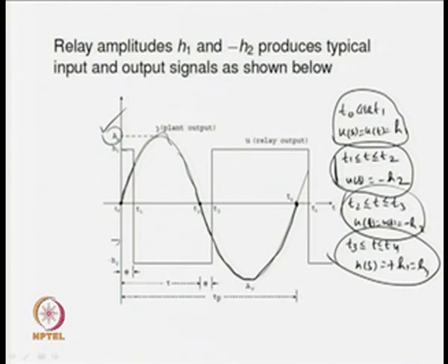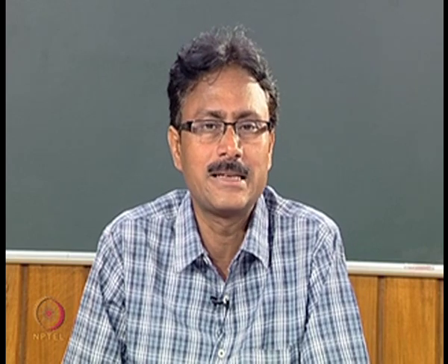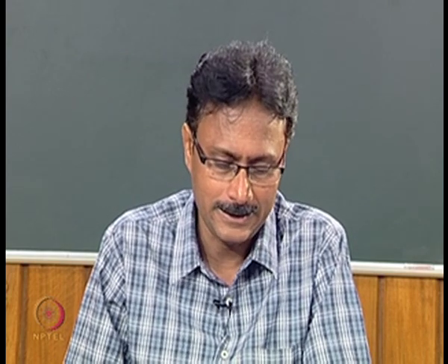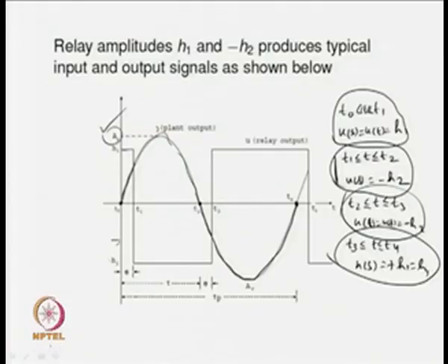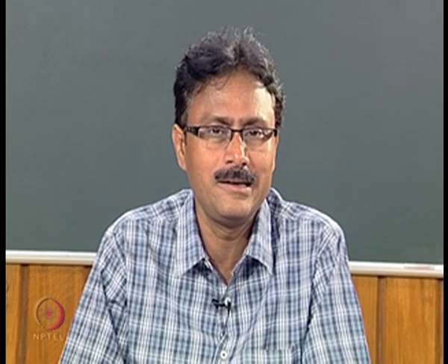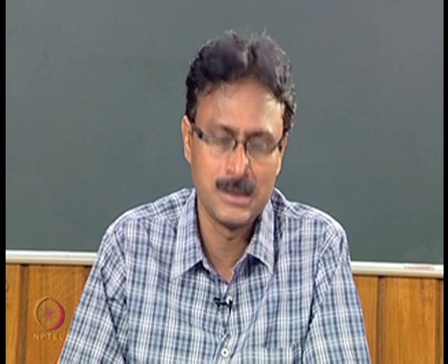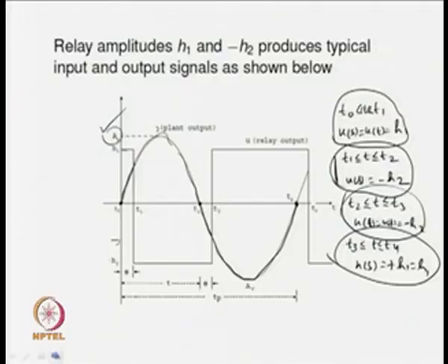Why will those expressions be exact? Because we are not making any sort of approximation in our analysis. Rather, we are employing the state equations for finding the expression for the output, and these are exact expressions without any approximations, unlike the describing function case where you approximate the relay by an equivalent gain. So no approximations are used in the analysis, therefore the expressions we get will be exact.